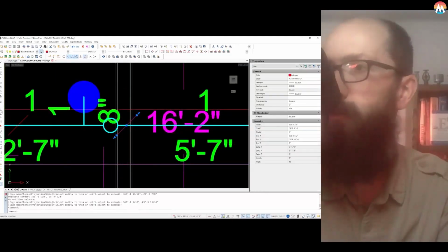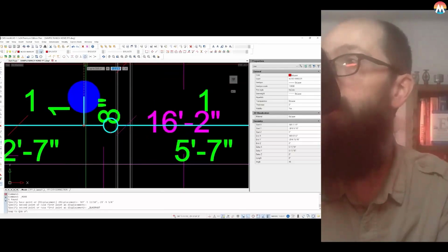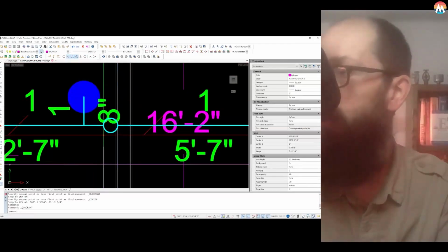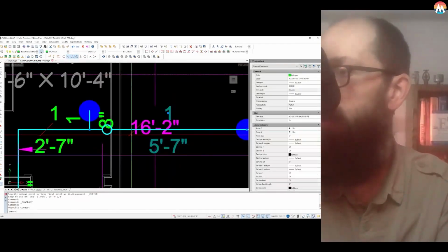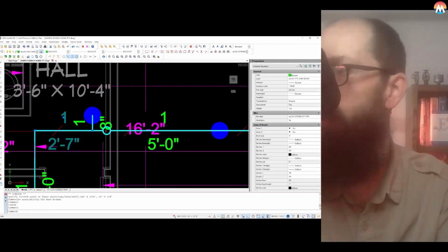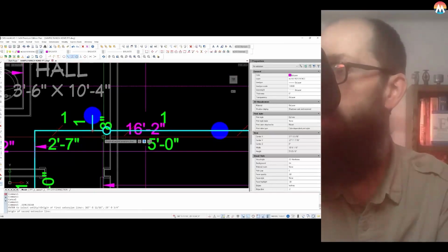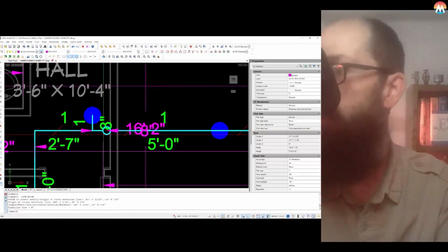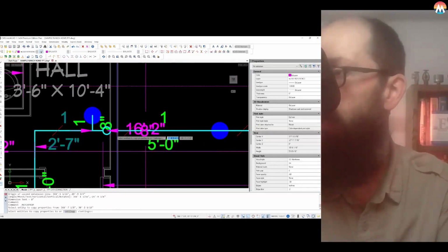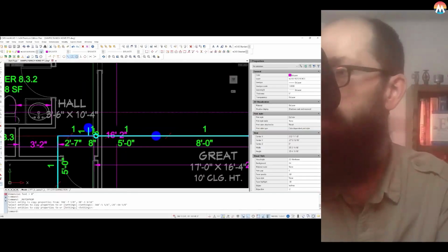And this hanger should be moved now from this point to this, whoa. There we go, center somehow. I turned on quadrant all the time. Now we need to adjust this dimension. Instead of going from there, it goes to here. And then now we need another dimension. There isn't one in between here, so I'm just going to go from here to here. It's 8 inches, and that's totally the wrong type of dimension. But if I go to match properties and touch one of these that are right, and then touch part of it, it fixes it. So that little pipe is 8 inches.